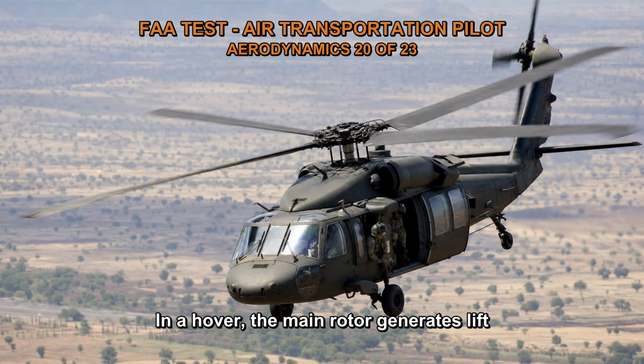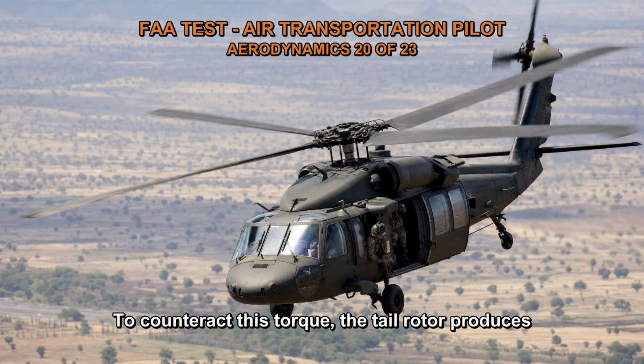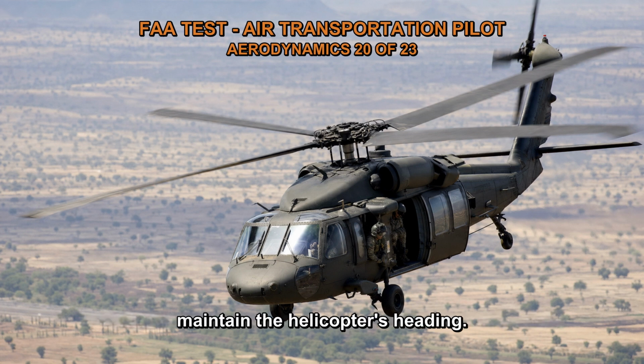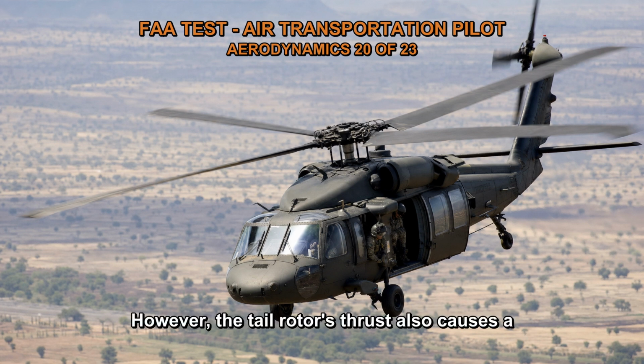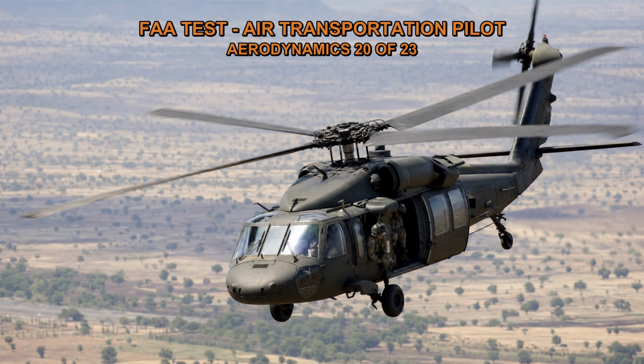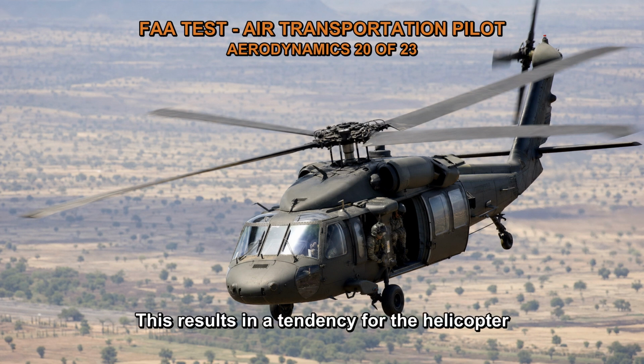In a hover, the main rotor generates lift and produces a torque that wants to rotate the helicopter in the opposite direction of the rotor's rotation. To counteract this torque, the tail rotor produces thrust in the opposite direction, providing anti-torque to maintain the helicopter's heading. However, the tail rotor's thrust also causes a lateral force that tends to push the helicopter in the direction of the tail rotor thrust. This results in a tendency for the helicopter to drift sideways during a hover.